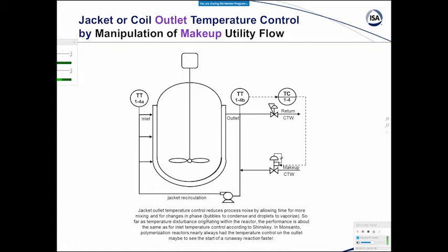So particularly if you've got the steam and water being mixed, you got this problem of differences in phases. Bubbles to condense and droplets to vaporize. It gives it time for that to happen. If you have bubbles or droplets hitting that sensor, you got a very erratic measurement. So again, you want to make sure that you have a single phase.